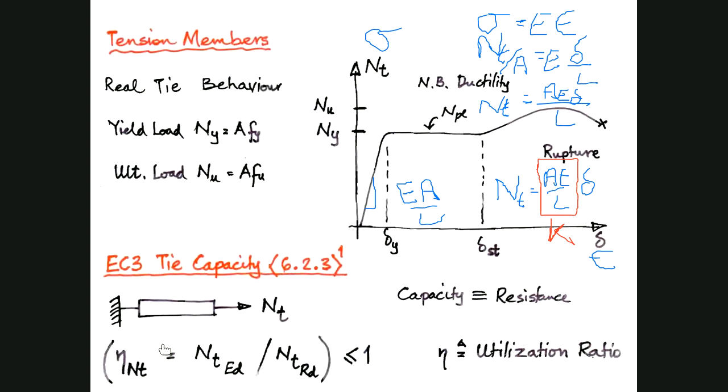And then in our design, we have the yield point that happens here. This is where it doesn't become linear anymore between load against displacement, and that's described as NY and displacement delta Y. We have a plastic region here, the NPL, which is effectively after it yields. And then we get some strain hardening after that. Strain hardening means that as we still stretch it a little bit more, we end up putting more force into it until we get to the ultimate force here, Nu, and eventually it's going to rupture at the very end.